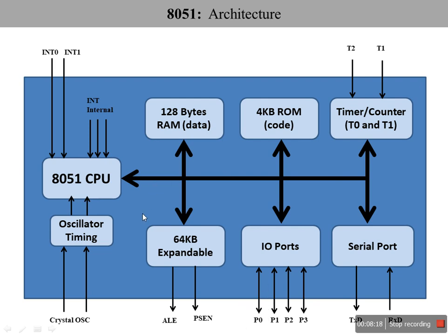Then there is a facility here. Assuming that your application size exceeds 4 kilobytes, probably say 5 kilobytes, in that case we can add some more external memory to this IC. It is possible to add external memory, either a RAM or a ROM, depending upon our requirement.